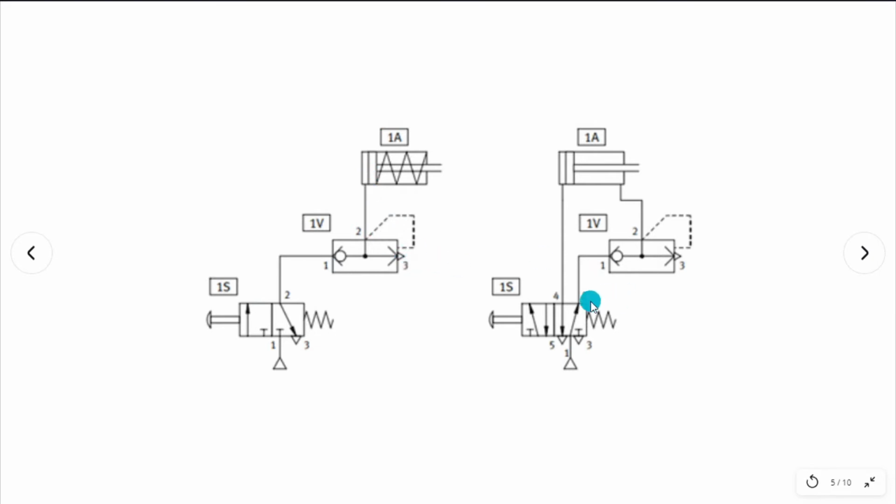Going to the next example, it is the same way, now with the use of a double acting cylinder. When you press your directional valve, it will change position and let air pass through, extending your cylinder 1A. The pressure buildup in this part of the piston will pass through the pipes and then move out of the quick exhaust valve. Due to this quick exhaust valve, the cylinder extends faster. But in the case of retraction, it will move as a normal direct actuation circuit.